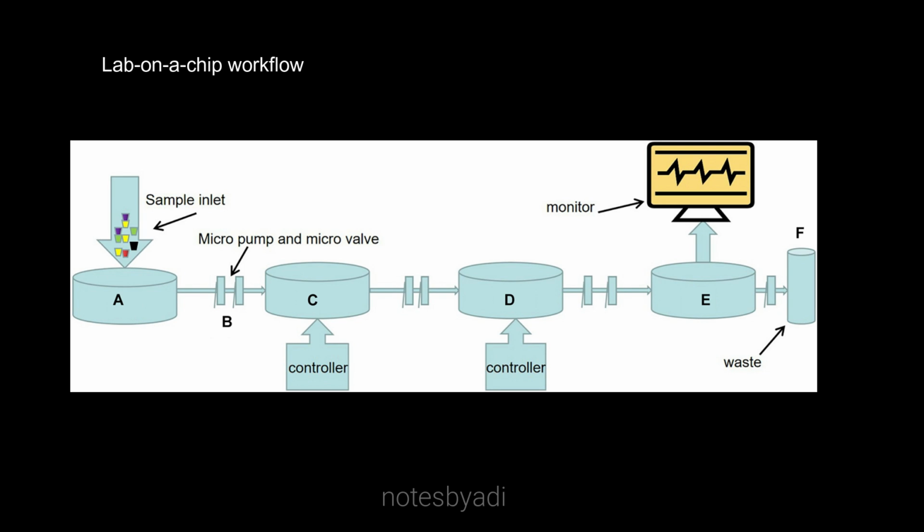A lab on a chip involves six main parts: the sample injection, followed by a large number of micro pumps or valves on the chip that can precisely control the flow direction and the flow rate. Then, the sample preparation includes the capture of the pathogen using cell lysis or nucleic acid extraction, etc. This part often needs external electric field or a magnetic field or even ultrasonic sound waves.